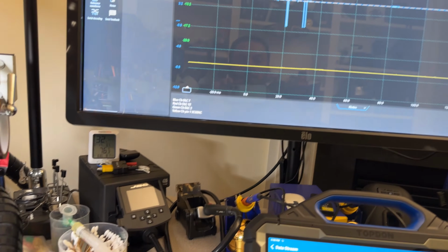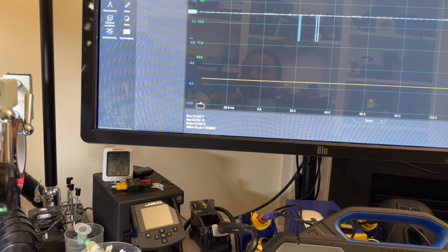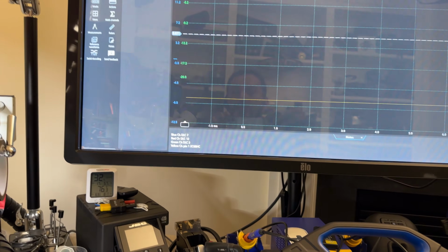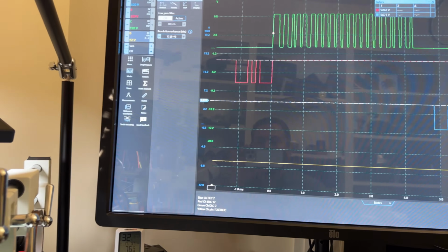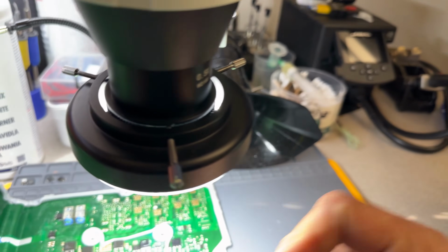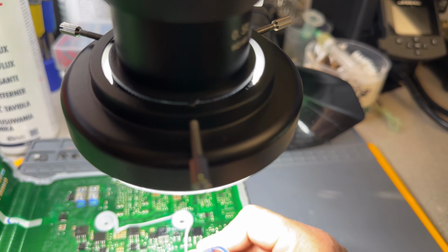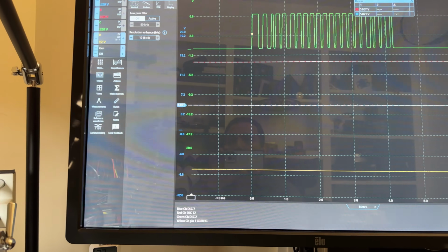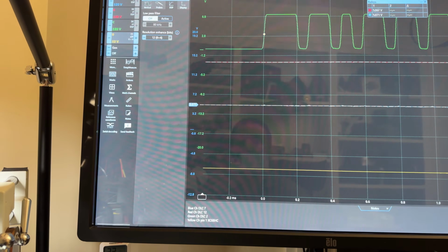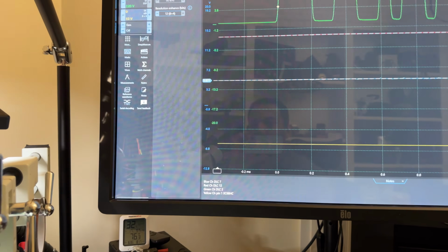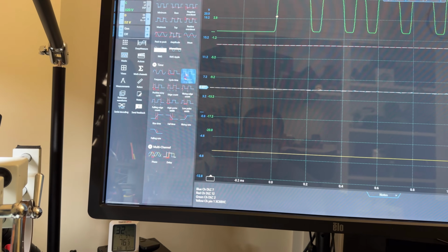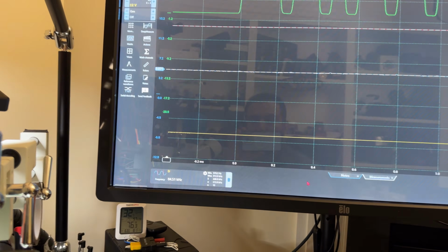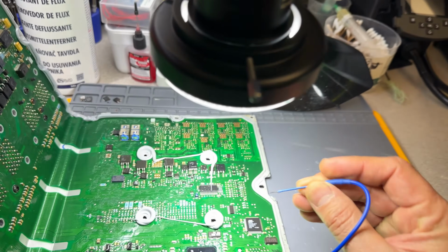I'm going to have to change the speed. The voltage and the speed are going to have to change a lot because this is a very small signal. So I'm putting them into 2 volts and I'm using that. So let me make sure that we can capture that data. I got to go faster. So let's go into 200 microseconds, and I'm going to put a measurement into frequency on channel D. That will tell us when we are connected and we are reading anything.